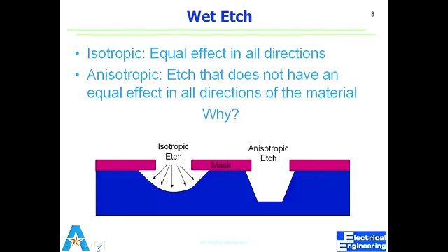What would be the mechanism for anisotropy for wet etch? Crystal structure. Of course, that's what I said. It depends on crystal structure, but why? Different crystal planes will have different numbers of atoms that they present at that point that are present for reaction. So even if we start on a plane surface, after a while, the etchant starts etching one particular direction much faster than some other.